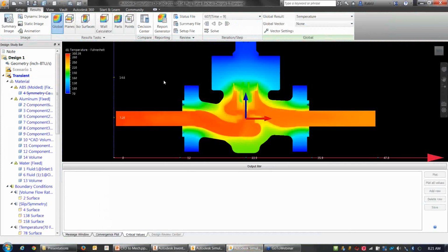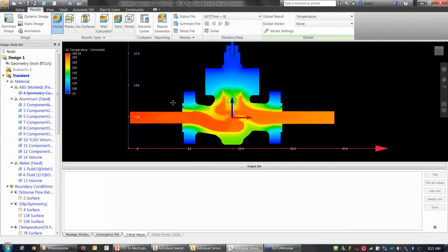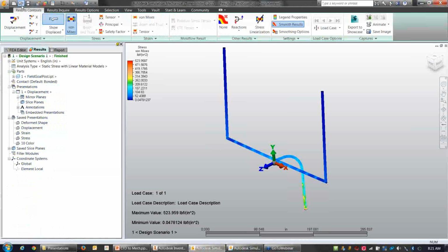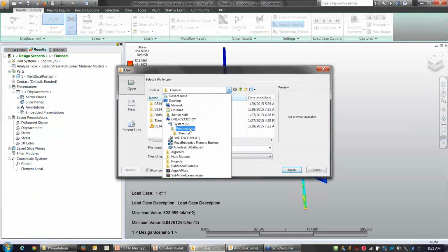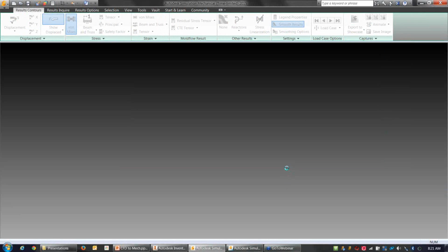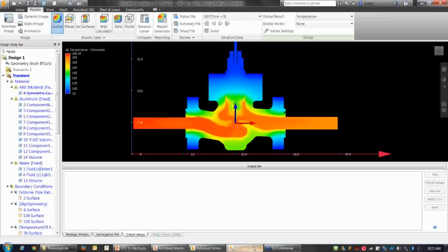As we can see here, it's again going to be just as simple, but this thermal analysis really plays onto the strength that CFD can offer, and that's the coupled fluid thermal flow. So we'll go into mechanical. This model's already been set up. It has been solid meshed and everything to make it a little bit quicker. I already have the fluid flow results here, because the fluid analysis can be relatively long, and then throw in the thermal.